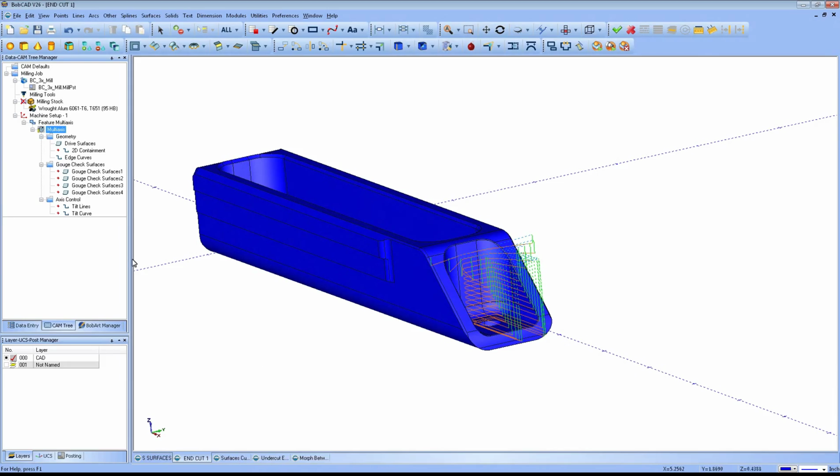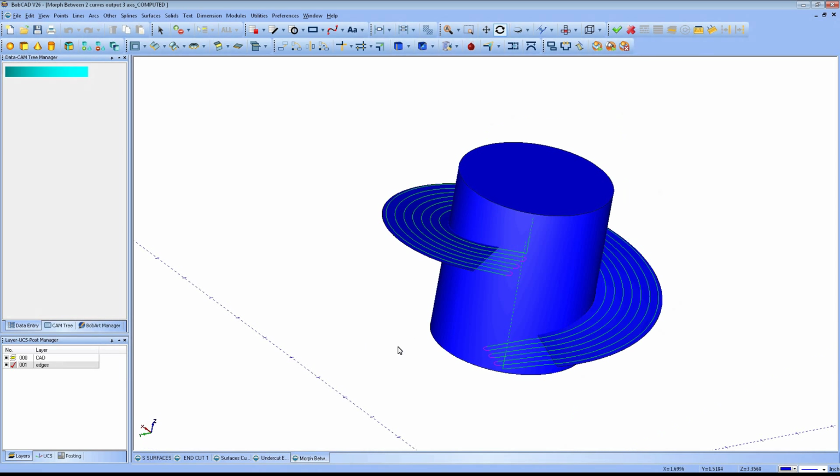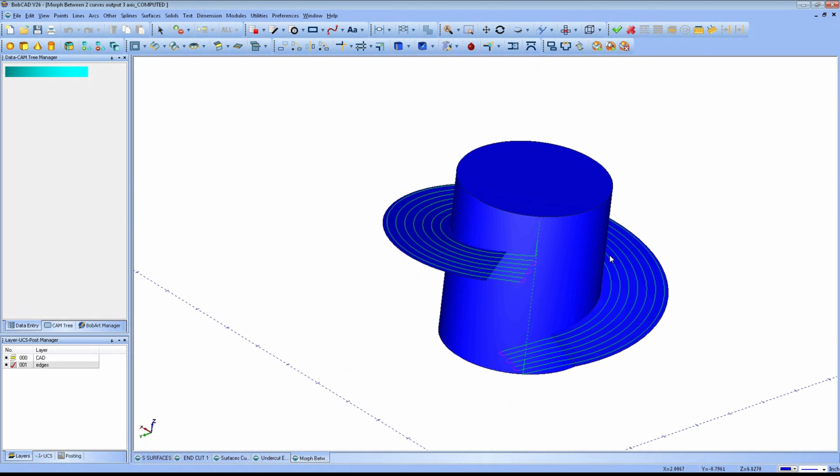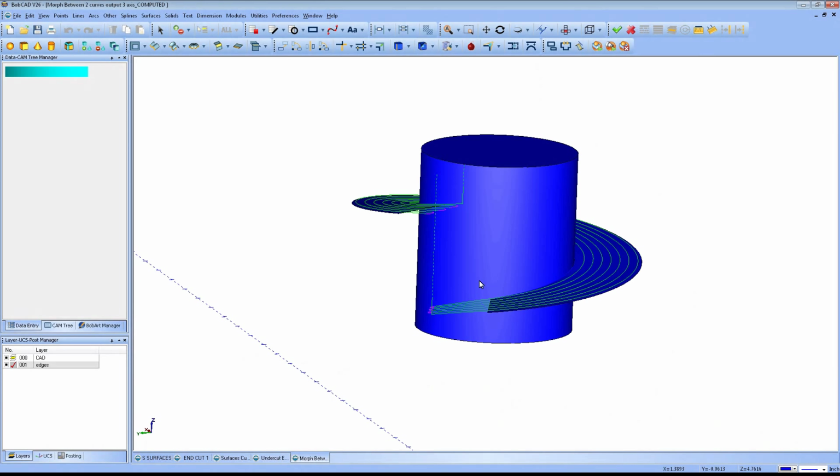Another example of this is this type of cut here. This is a shape where you might want to just run around this, stepping inward, cutting this ramp out. Without these toolpaths, you would have to get the intersecting edge of the two surfaces and create your own offset of the tool, because a toolpath you draw yourself won't do any offsets. And then copy it over and use the 3D project or 3D engraving toolpath to cut that out.